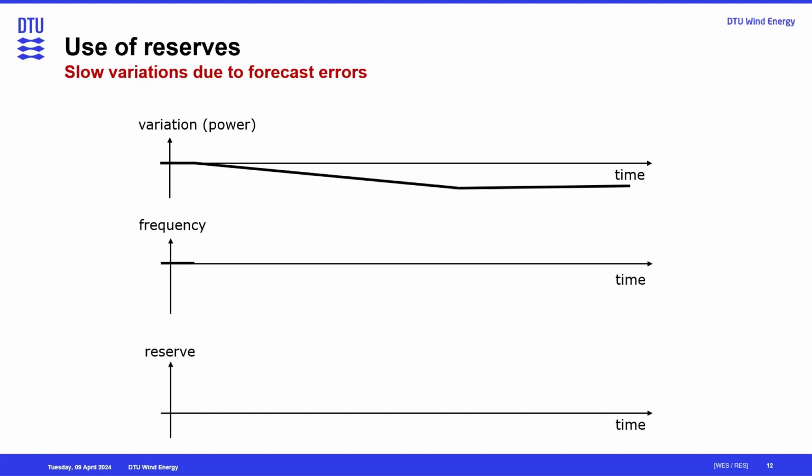So as close as you can maintain it, for example in Europe, to 50 hertz, the more stable and secure your power system is. And it's a global signal. So you measure it in a synchronous power system: in Switzerland, in Germany, in Italy. Anywhere you measure it, it's the same signal you get.